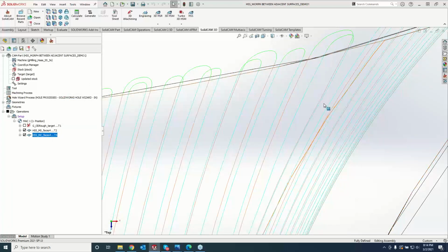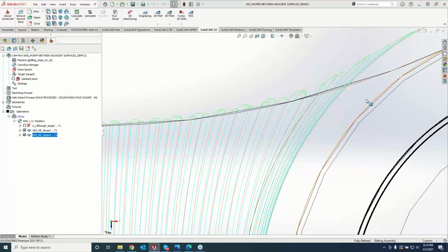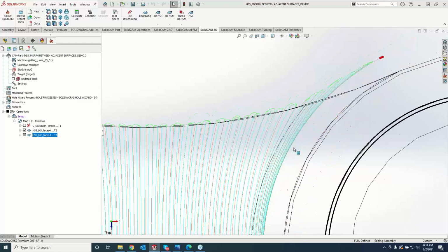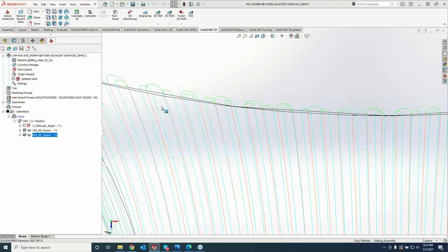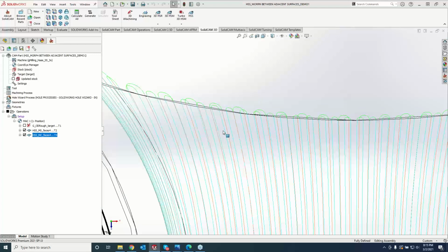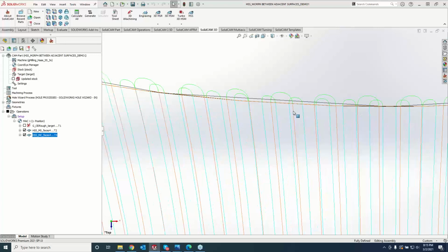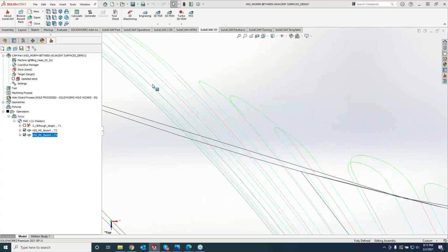Same results. Okay. So, I mean, we are getting the same curvature with the tool path. Everything is identical from one to another. The only difference I see is we have just a little bit of a step over from one to the other. Because I can see right towards the center here, our morph between boundary curves is quite a bit larger. But if we get over to the corner area, it's still a little bit larger here, not nearly as much though.